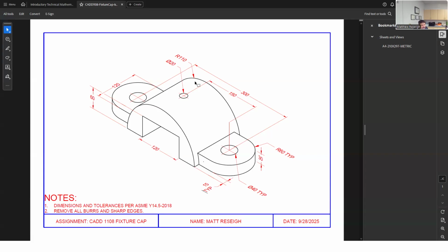This is by radius here. So 110 millimeter radius. So that would be 220 out at least to the ear. Well, 300, this is a better one. 300 millimeters from hole to hole. And then I just need the radius of this round on the edge here. Sometimes you call it a fillet, but this would definitely be considered a round. And I would almost call this an ear on this part, these two little tabs that are flat.